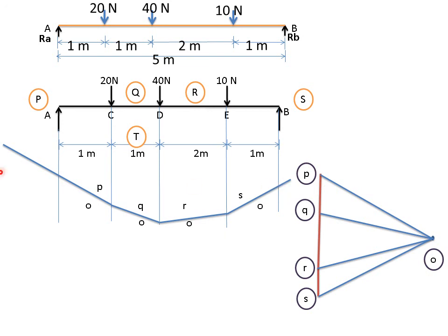Now what you do? Join the first point and the last point. So I am drawing a line here. Same, parallel to this line, you have to draw a line from this point in this diagram. So say it as TO. So you just draw the line parallel to this. Where it intersects this vertical line, from here you can give the name to this as T. So PT is called reaction at A. See here, force PT. Between P and T, what is there? A. So that is reaction at A. And TS, between T and S you have got RB. So TS is nothing but reaction at B. So this is called the graphical method to find the reactions.